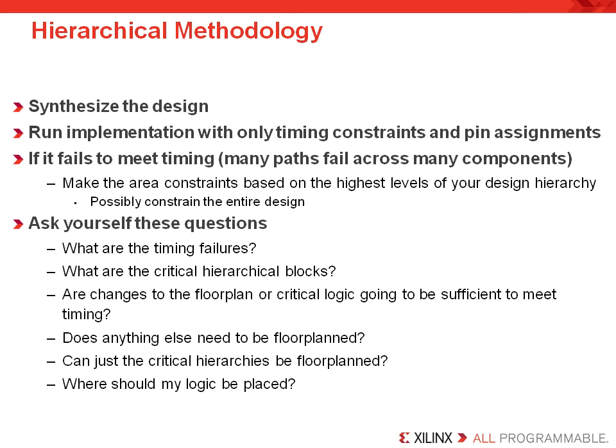In order to create a hierarchical floor plan, first synthesize the design. Then run the implementation with only timing constraints and pin assignments. If it fails to meet timing, make the area constraints based on the highest level of your design hierarchy.